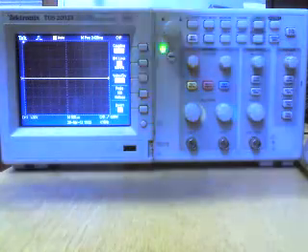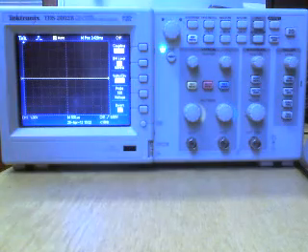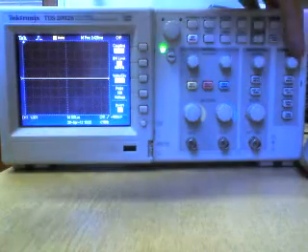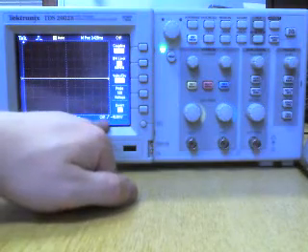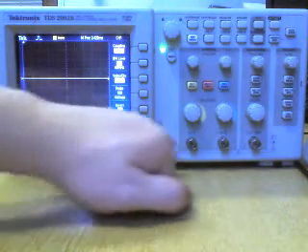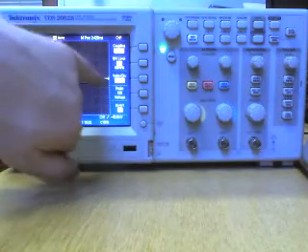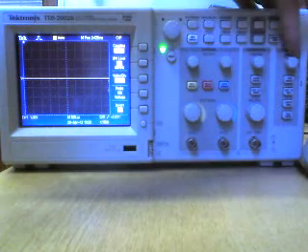Okay, and you can see our little arrow up here. It's at the beginning of the screen now. And to make life even easier, over here we've got our trigger level. Now, down on the menu it tells us what channel we're triggering on. So channel 1 is what we're going to trigger. So channel 1's the waveform that we're going to stabilise, whatever's plugged into here. And we have an arrow on the screen on the right hand side that corresponds to our trigger level.